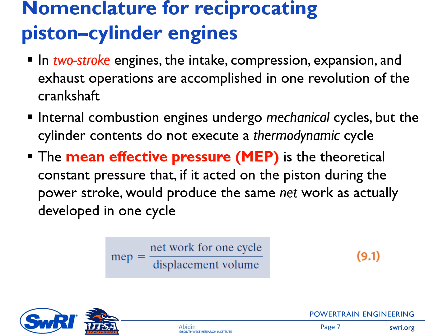Internal combustion engines undergo a mechanical cycle, so it means we have a crank rotation there. We have crank rotation and then transfer this rotation power finally into the wheel. So they undergo a mechanical cycle, but the cylinder content does not execute a thermodynamic cycle. If you look at your car engine, it sucks in fresh air, and then at some point the fuel is introduced to the stream, and there will be a combustion, and then the burnt gas will be discarded out of your car engine.